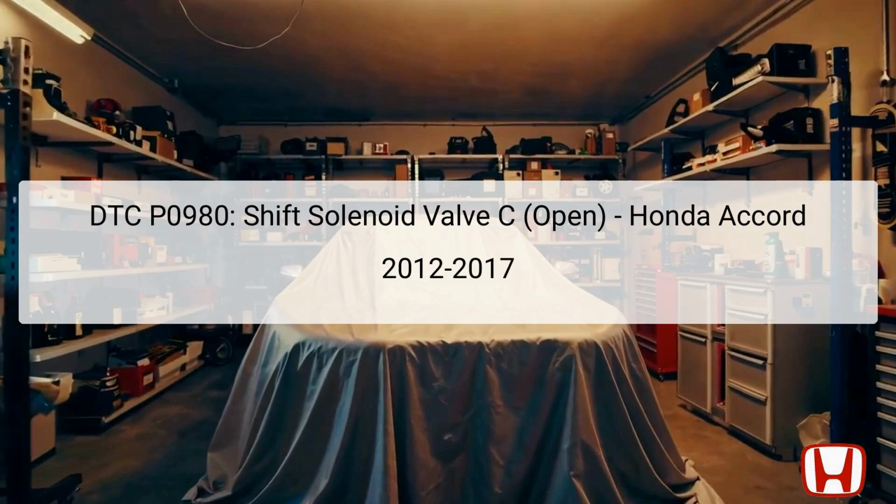The DTC, Diagnostic Trouble Code P0980 refers specifically to an issue with the shift solenoid valve C in Honda Accord models manufactured between 2012 and 2017. This error indicates that there is an open circuit in the shift solenoid valve C, which is critical for regulating hydraulic pressure to the clutch.